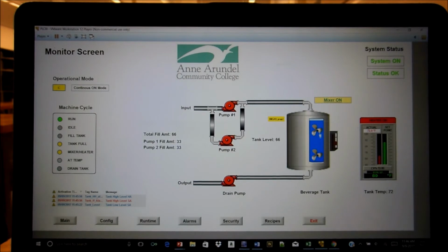All these parameters, we have them in registers, so we can scale what this tank looks like as full, and it always looks full because we're reading from a register value, not a constant number. Down here we have some faults, and when they're in red, they're active faults, so the high signal is active right now because we're still at the high level. The ones that are in blue are faults that have cleared away. So now that we're not at the high level, we can just acknowledge that and it clears. And we'll go through the routine again, and it'll just do that continuously.